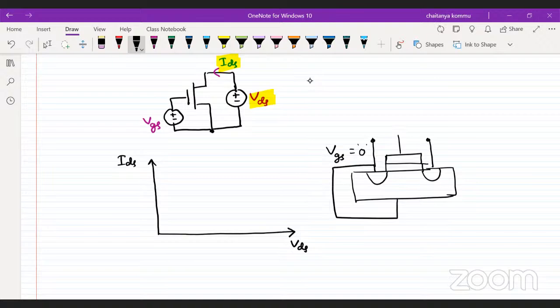For example, if you walk on a road outside, only when there is a road can we walk. Otherwise, how can we walk? Where would we go? Similarly, the same scenario applies here. If the channel is not present, no matter how much potential difference we apply between the drain and source, the carriers cannot transfer. Therefore, as our friend told, the IDS value is equal to 0. Whatever the change of the VDS value, the IDS value is equal to 0.